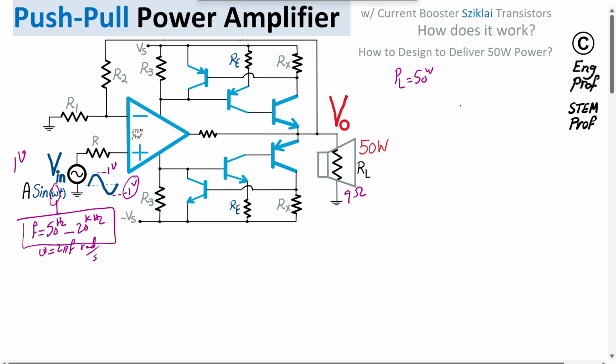Of course, you can see that the op-amp is in negative feedback configuration because the output of the op-amp is connected to the negative terminal, and when the input is trying to rise, the output tries to increase as well. So during the positive cycle, we have the output rising, and then via the voltage division between R2 and R1, the negative terminal rises as well. So the op-amp is clearly in negative feedback configuration, and because of that, whenever a sinusoidal voltage is at the input, we have a sinusoidal voltage at the output as well. Because we have a resistive load, the voltage of the load, by Ohm's law, is RL times the current of the load, and the current of the load is this current.